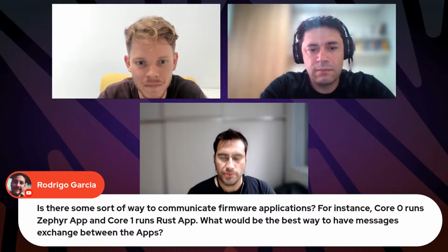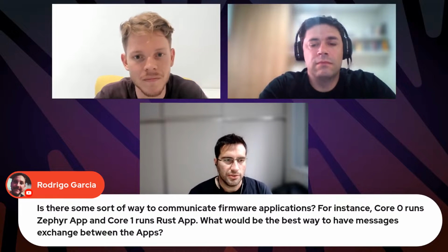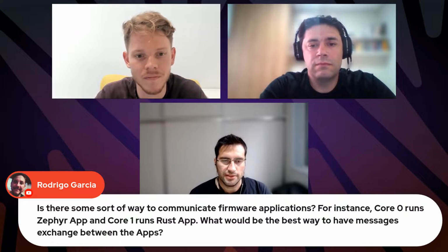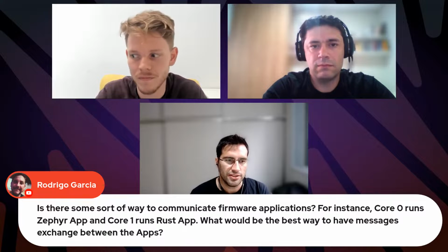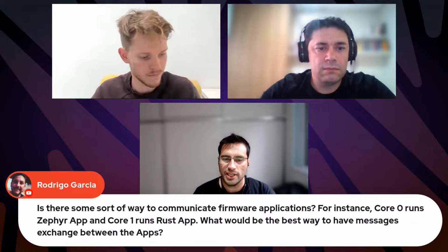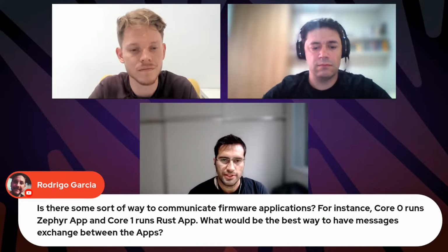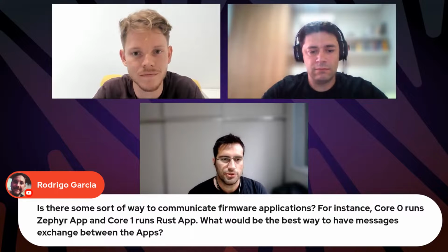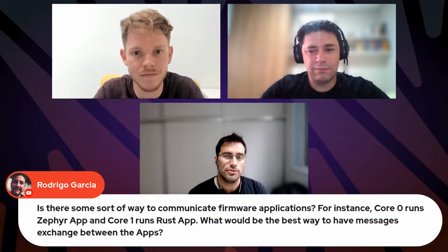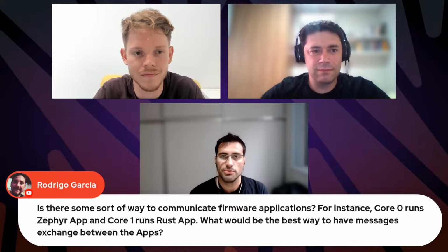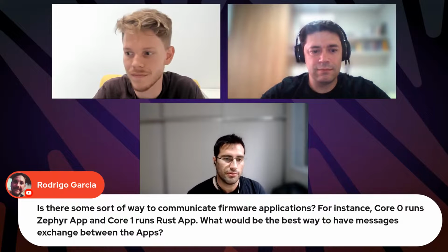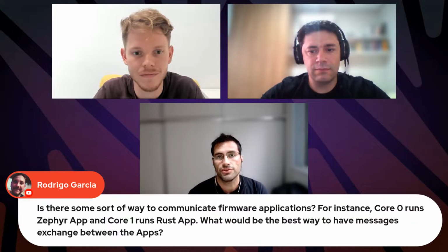Yeah, so when it comes to Zephyr, we implemented a soft IPM. IPM is interprocess messaging. In Zephyr, the IPM is the interface responsible for exchanging messages between both cores. This IPM interface has 4 channels. Channel 1 is for the Wi-Fi packets, channel 2 is for the Bluetooth packets, and channels 3 and 4 are for application custom packets.